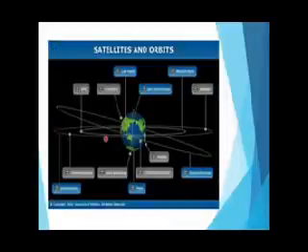One of the most common methods of TV signal distribution is via satellite. A communication satellite orbits the equator about 22,300 miles out in space. It rotates in synchronism with the Earth and therefore appears to be stationary. The satellite is used as a radio relay station. The TV signals to be distributed are used to frequency modulate a microwave carrier and then transmitted to the satellite.